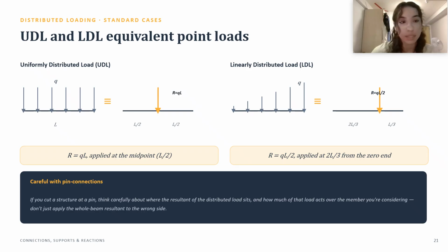Instead of doing all that integration, which only comes in handy when the shape is really weird, what you will do is place the resultant force on the body in the middle of where the arrows are. So take the length from the first arrow to the last arrow, divide that length in half, and that's where the resultant force arrow should go.